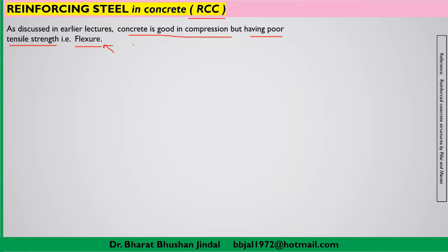But if that member is made up of concrete, as we know that concrete is weak in tension, then it will not be able to take care of all the tensile stresses, due to which cracks will be observed in the member. And when cracks are there, definitely the strength of the member will reduce, your structure will not remain durable, and there are very significant chances of failure of the structure.